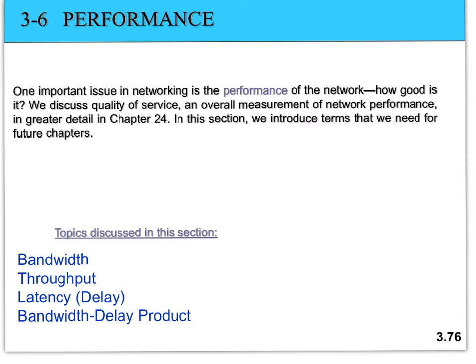So last time we started to talk about the theoretical data rates for two cases. For the case of noiseless channel, we said that the theoretical data rate is double the bandwidth in terms of hertz multiplied by log 2 of L, and this is Nyquist. This does not consider noise on the transmission medium by any chance.